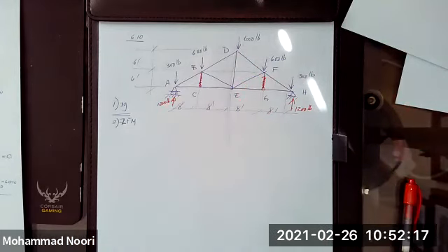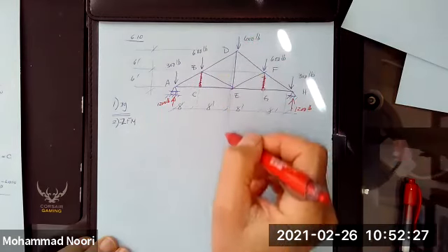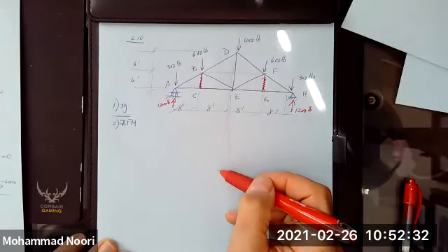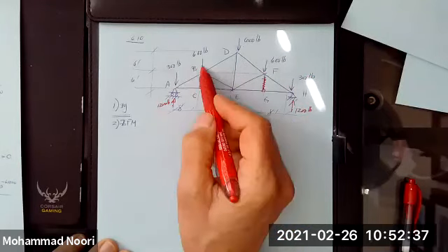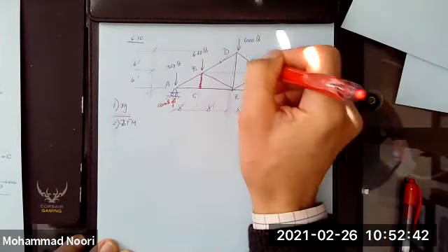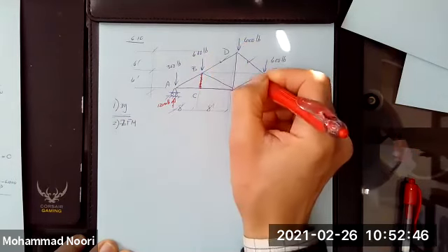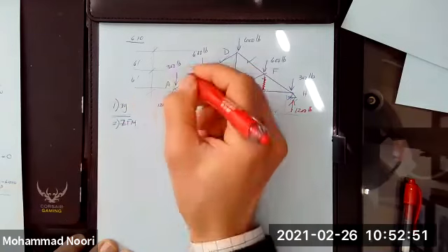That's part number 1. Second, even more important, if you have this symmetry, load symmetric, structure symmetric with respect to the line of symmetry, all those members that are symmetric carry the same load. That is, this member and this member, the load in these 2 will be the same.